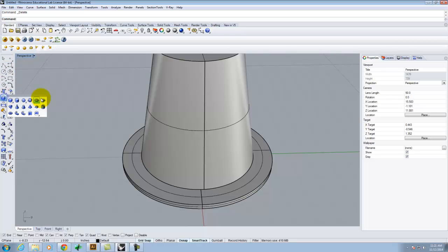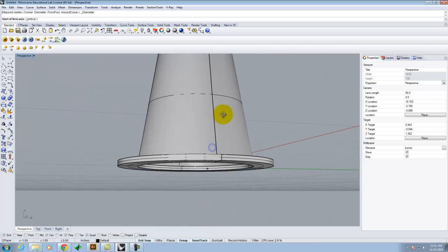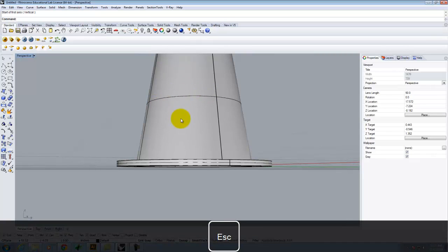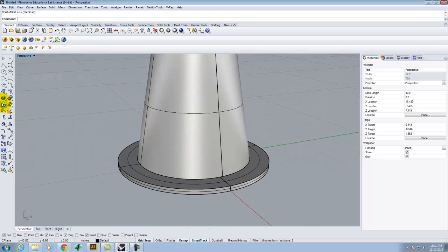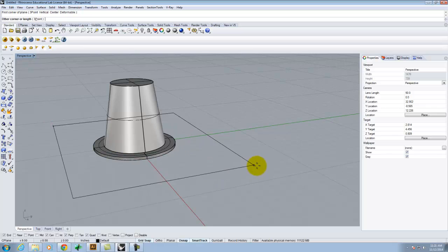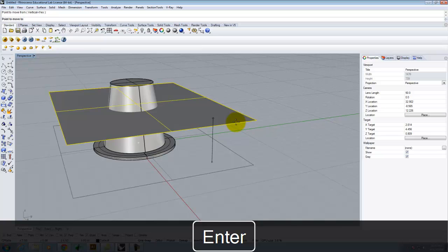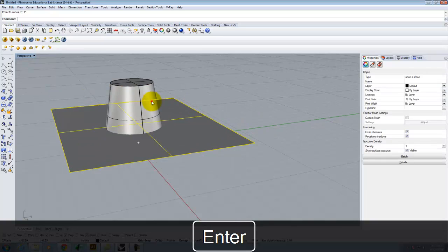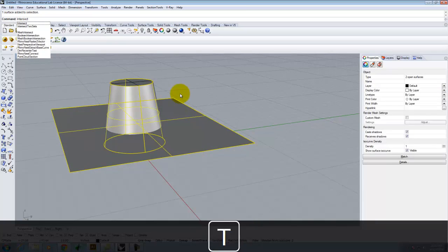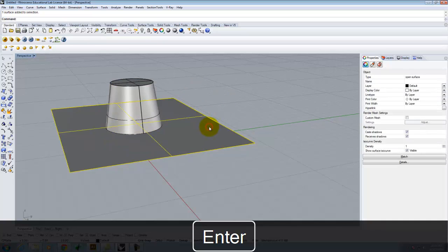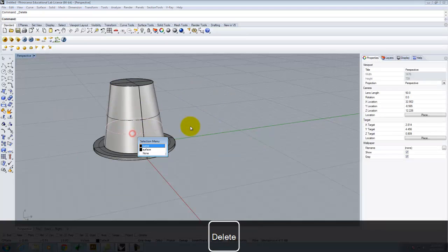I'm going to pick an ellipsoid here, and I'm going to pick a by diameter. And oh, you know what? I need a curve that's up here a little bit. So let me do a quick intersection, just for accuracy purposes here. Move vertically by, I don't know, 2 inches, something like that. I'm going to intersect these two together, give me that curve. I can get rid of this. It just gives me that curve to work from.